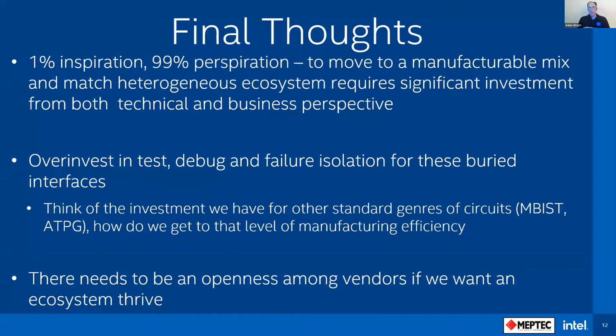So it's always been a heavy lift to get extra pads and probes. We've definitely looked at that, but for the most part, in the PSG realm with the FPGAs, we don't typically do that. I don't know if that's a standard approach at broader Intel, but we don't typically add test-only pads to look at things. We already have issues with getting enough probes into the area. Adding extra pads is a heavy lift.